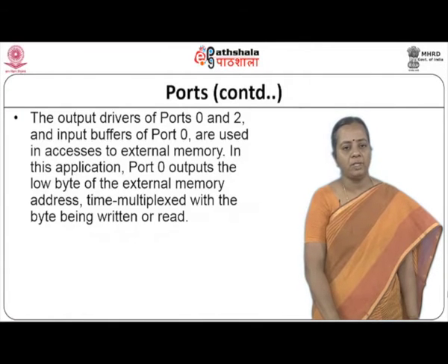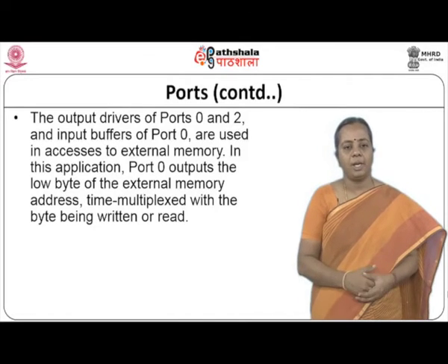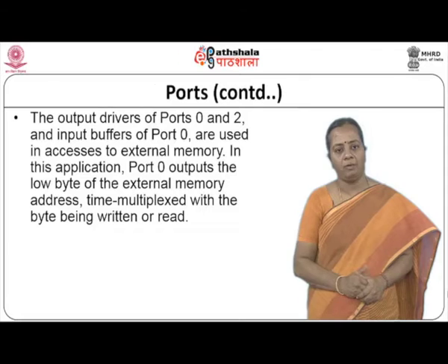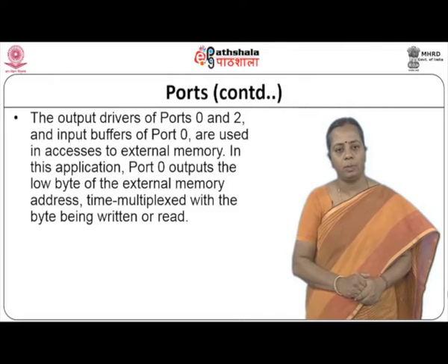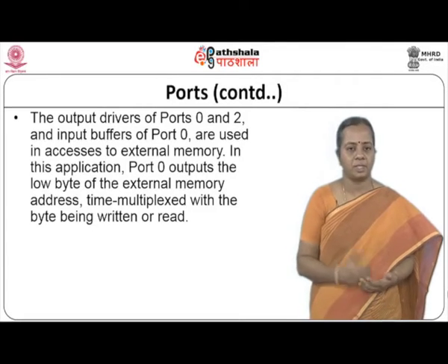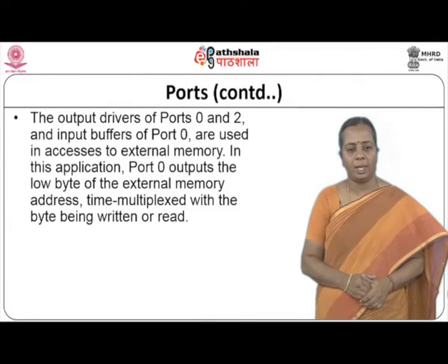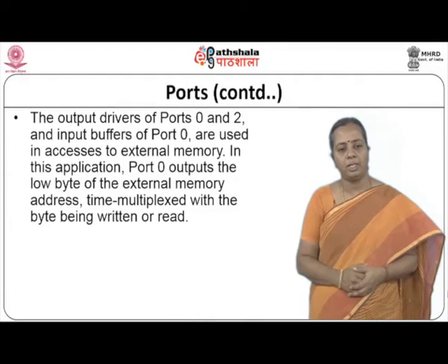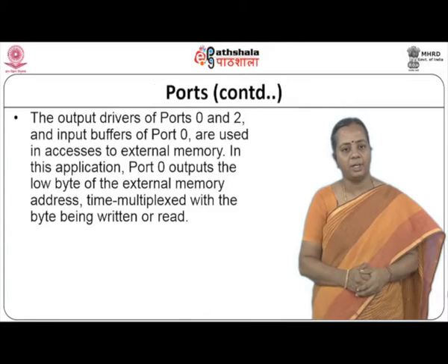The output drivers for port 0 and port 2 and the input buffers of P0 are used to access the external memory. As we have gone through, this microcontroller has its own memory, but it is of very little space, so that may not be sufficient to hold the data. So, either the program or the data can be read from external memory or written to external memory.